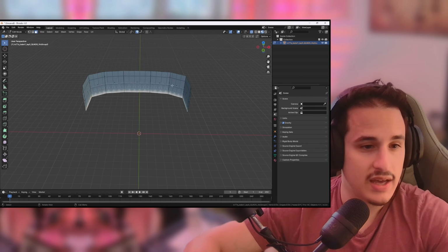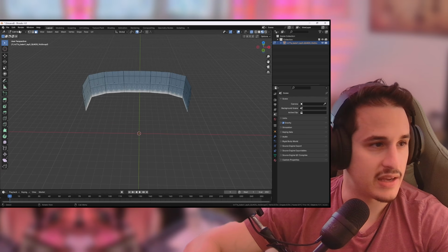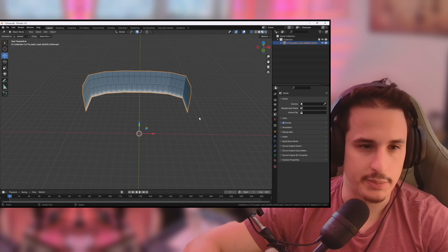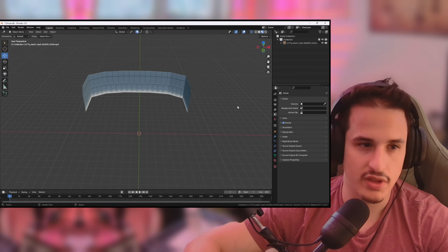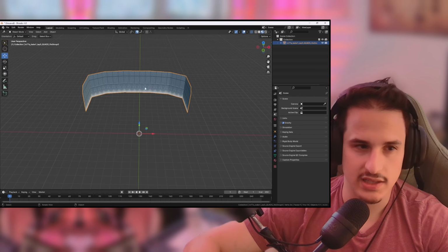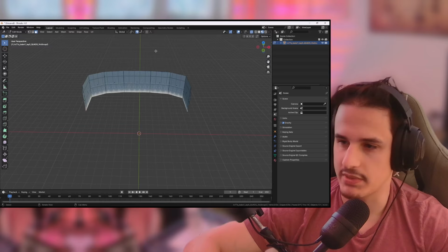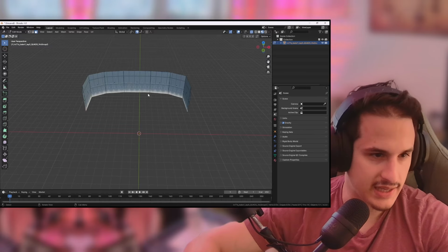So if we want to make good tiles, the way to do that is the following, specifically for walls. I'm going to go into edit mode. If you want to switch between object and edit mode, you select something and hit Tab. It should tab you back and forth. If that doesn't work, just click and then you can hit Tab. Sometimes it's finicky. Blender can be like that.